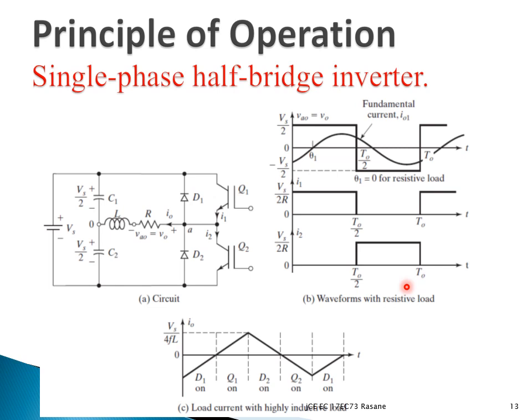Okay. So for the load, it will be reversed, but for Q2, you have to show it in this direction itself. Now this is the load current. Now in load current, you can see we have got how many switches here? Q1, Q2, D1 and D2. Q1 and Q2 are basically the choppers and D1 and D2 are the freewheeling diodes, and they carry a current of the load whenever your chopper is off.